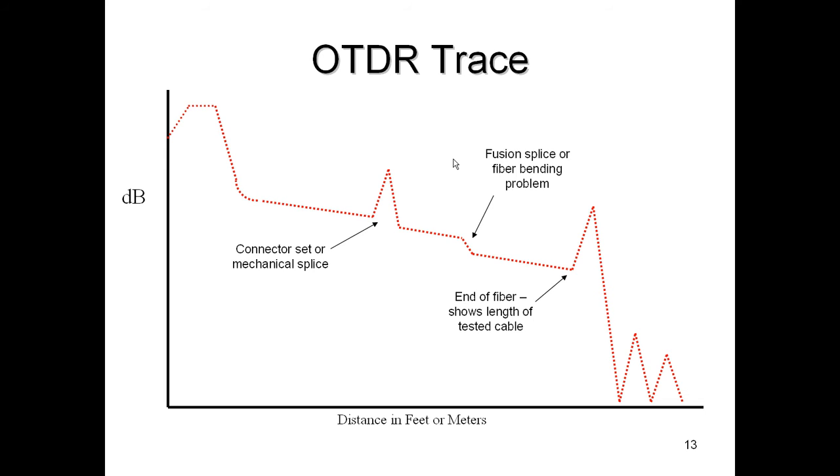One on the bottom is the distance from the OTDR, because you're going to connect the cable under test up to the OTDR, usually by using a box called a build-out box, which has known good fiber in it. It's the same situation we had with the optical loss test set, where we want to isolate our cable under test from our tester itself.